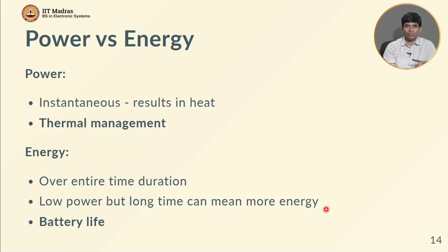So, your static power could potentially get to the point where it basically says, okay, now I still have static power and I am going to take twice as long to execute. So, therefore, the savings that you thought you had, or rather that you kept the energy constant, is wrong. I am actually consuming more energy than before, because it is taking me longer to run, and during that extra time, static power was still being burnt.